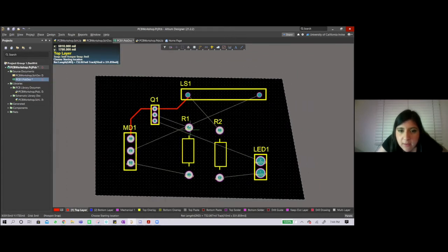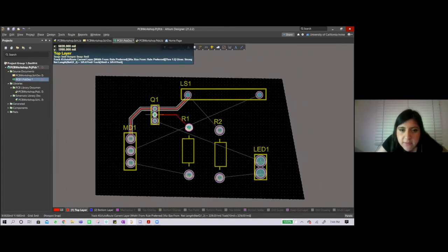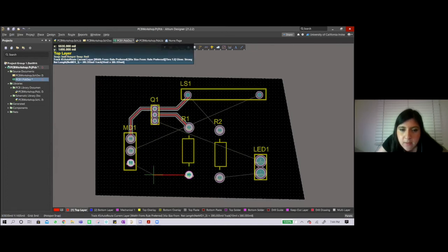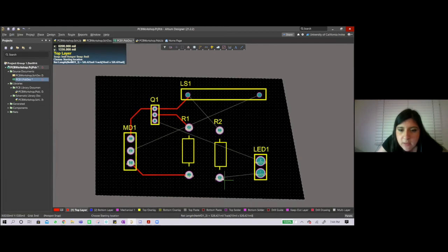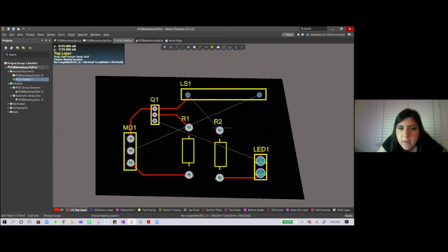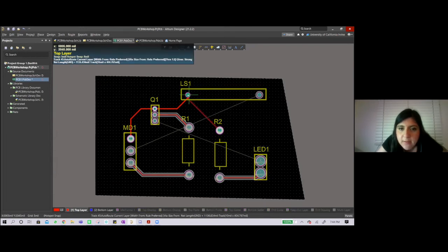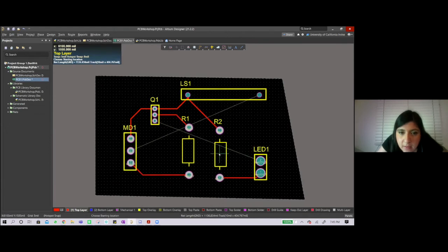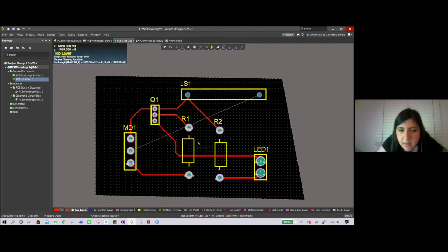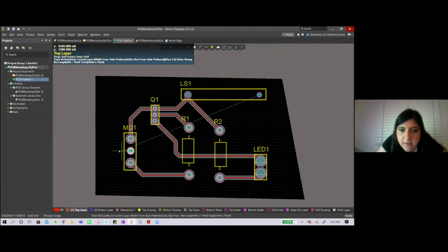And then this pin here goes to the MOSFET here. Sorry, the BJT there. And this resistor goes here. This one goes to that net there. And then we could also connect this one here. And lastly, since these are through-hole components, crossing the silk layer isn't really an issue. And lastly, we have this connection, and we could just go ahead and go up across the back.